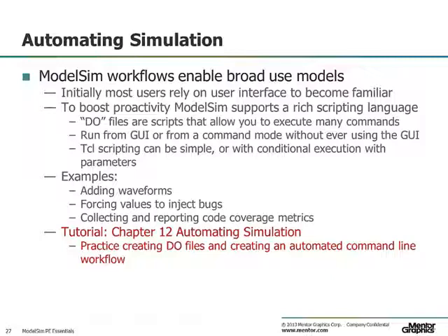Do files are scripts that allow you to execute many commands at once. The scripts can be as simple as a series of ModelSim commands that you ran through the exercises, with associated arguments, or they can be full-blown TCL programs with variables, conditional execution, and so forth. You can execute the do files from within the GUI, or you can run them from a command line prompt without ever invoking the GUI. This is one of the main methods for batch type simulation.